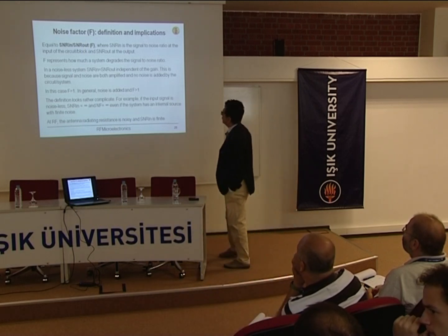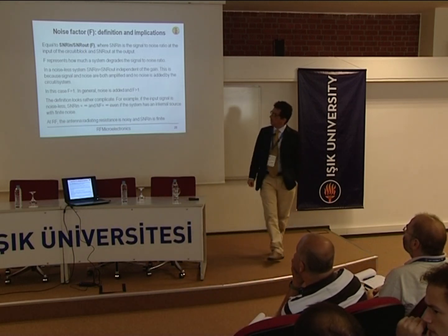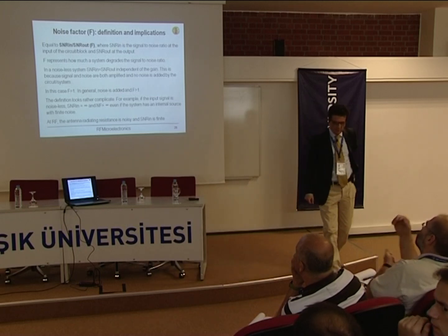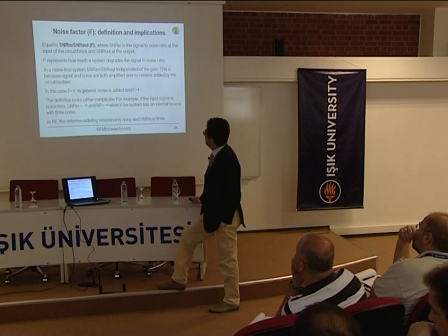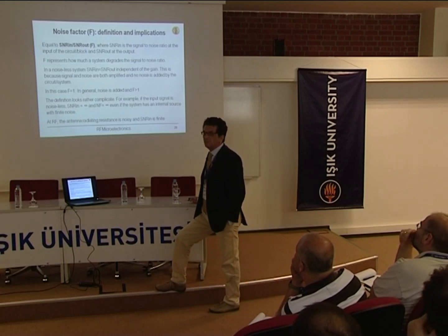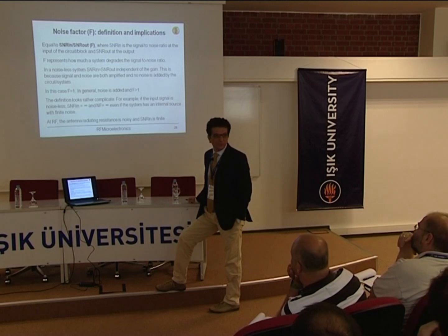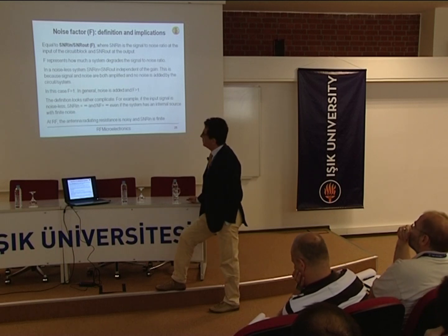Just the definition of noise factor and the implications. So the noise factor is defined as the ratio between the signal to noise at the input of a circuit over the signal to noise at the output of the same circuit, okay?